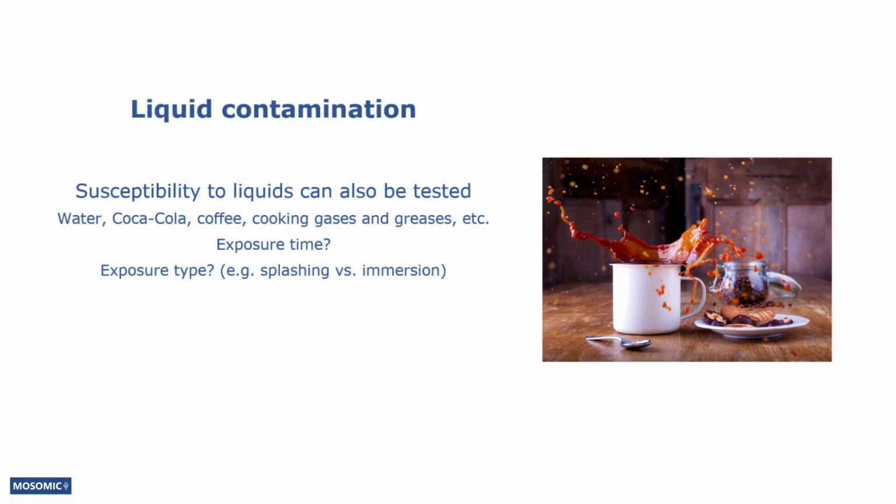The susceptibilities of MEMS microphones to liquids and other contamination that is not particles can also be tested. Depending on what the expectations for the immunities of the microphones are, the components can be exposed to, for example, everyday contamination such as water, Coca-Cola, coffee, cooking gases and greases, and so on. The results of a liquid test depend on the exposure time and how the microphone or device is exposed to liquid. For example, is the liquid splashed onto the microphone or is the microphone immersed?